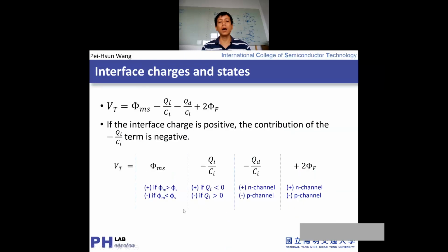So once you get it flat, we can consider what is the depletion type and what is the accumulation surface potential. And as we mentioned, if you get a positive surface potential, that means you apply the voltage on the metal side. You get an N-type channel because we get the electric field from metal to semiconductor. So under that scheme, it will work as an N-type condition. And also for depletion region, it should deplete the P-type region.